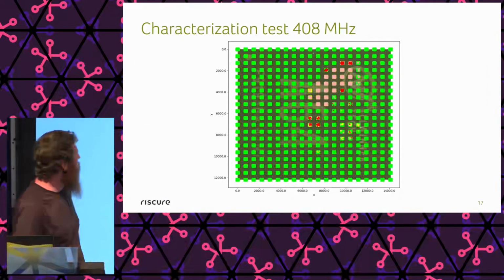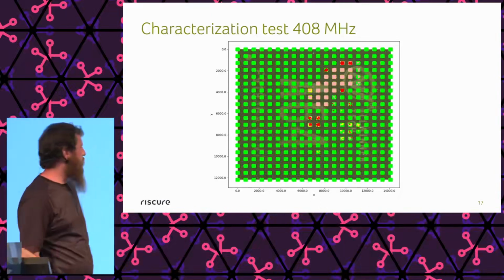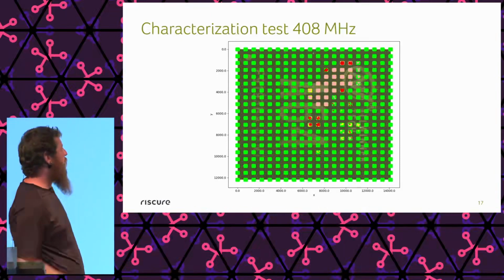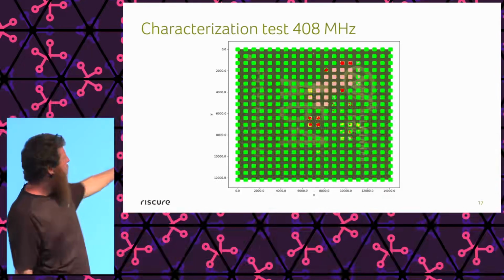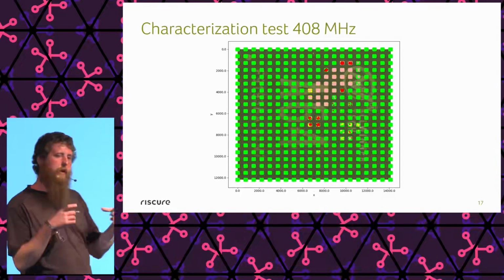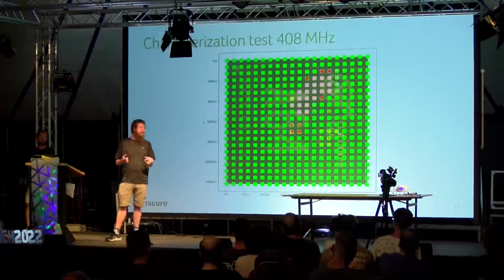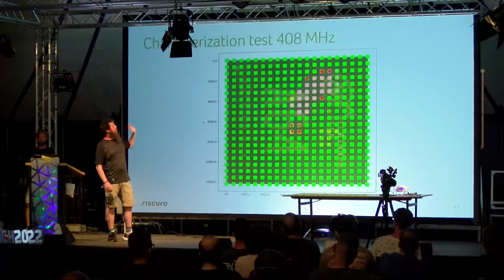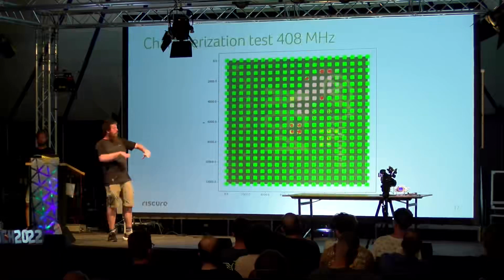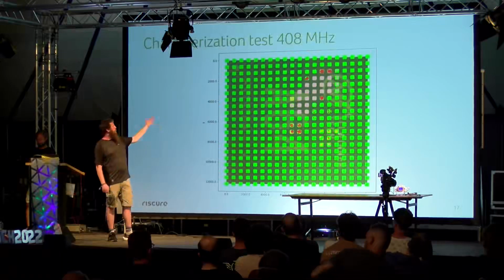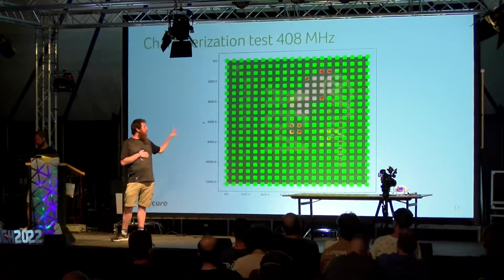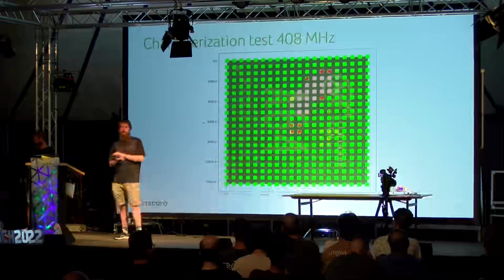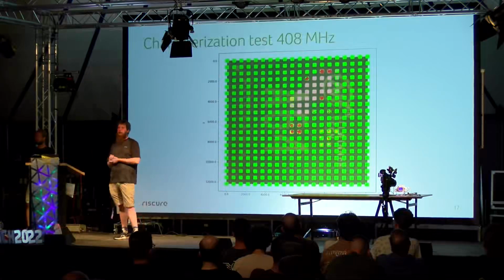It might not be so easy to see here, but this is a representation of the many glitching attempts we have done. The darker part in the back is an image of the packaging of the die itself, and we've divided that whole space into a grid. We can see all of the green spots are where we have had no effect on the device at all, so it's returned exactly what it should return. We didn't modify anything.